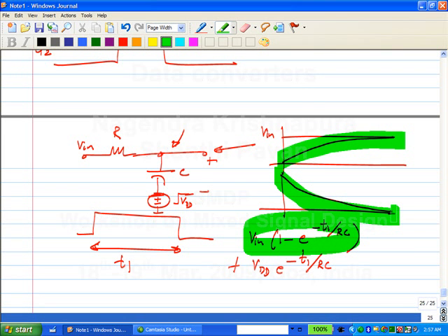Okay. So clearly what you have to do is to reduce this time constant RC as much as possible. Yes, sir. Vin is always much lesser than VDD. Yes. Right? So why not make that VDD contribution 0? That's correct. So he's overtaken me here, right? You can see that the only way to make this work is to make RC 0. That is obviously not possible, right? You can't make R equal to 0.